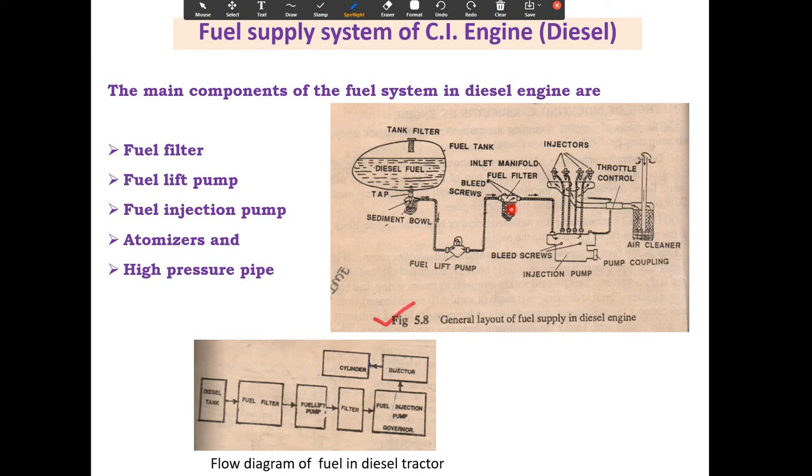It is a primary or secondary filter. That primary and secondary filter removes the coarse and very fine material or parts from the diesel. So clean diesel is provided to the fuel injection pump, and that fuel injection pump forcefully gives the fuel supply to the injector.